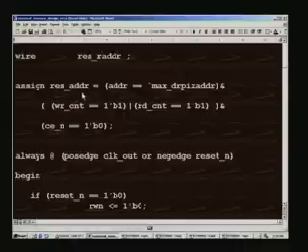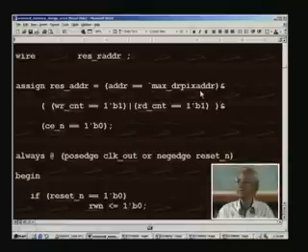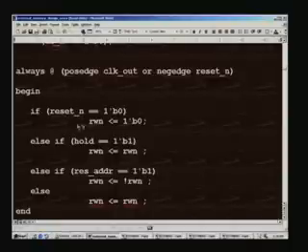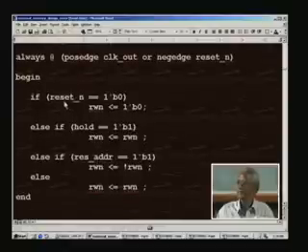So, the address resetting means the running address will go from 0, 1, 2 etc. up to 65,535. When it touches 65,535, this signal is created, and we have one register here for creating this RWN, which we have seen earlier, and this is meant for the selection of read or write. For example, if it is 1 it will be a read, otherwise it will be a write.